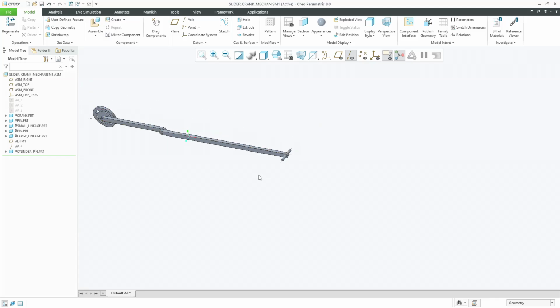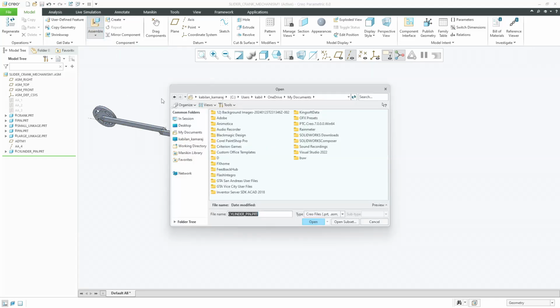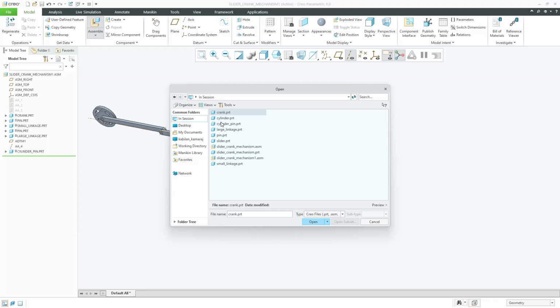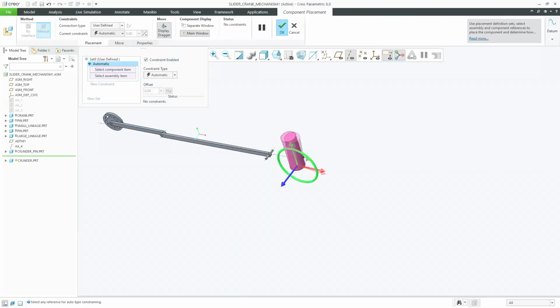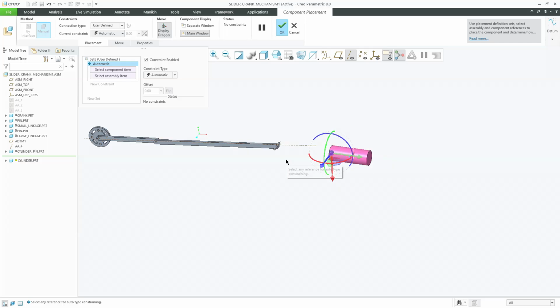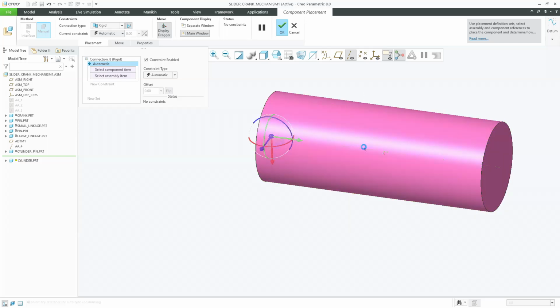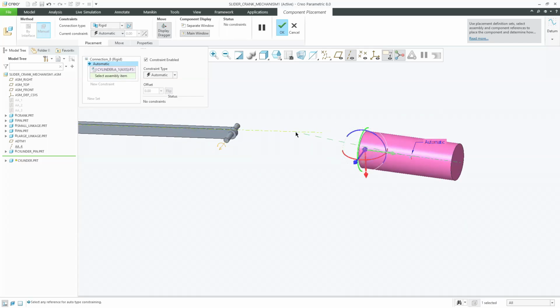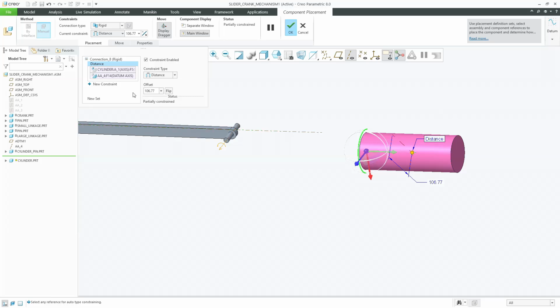The next part, I'm going to create an assembly of the cylinder, which is going to get a rigid connection, since this particular part is the only part which is going to have all degrees of freedom completely arrested, a perfect rigid connection. So I'm going to select a rigid connection here. For the first connection, I'm going to give a constraint between these axes which we have created.